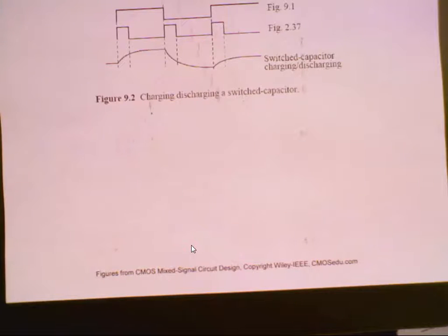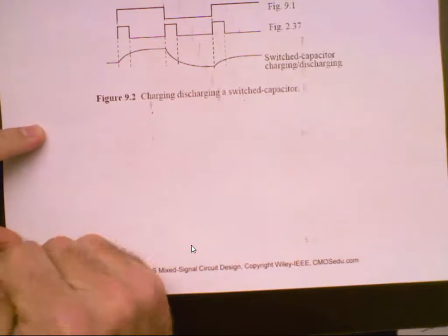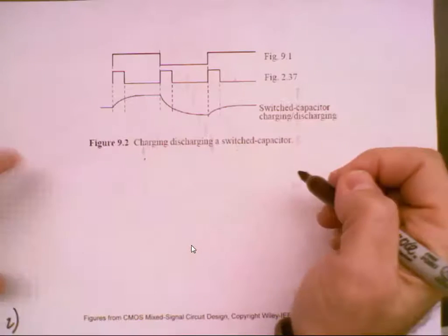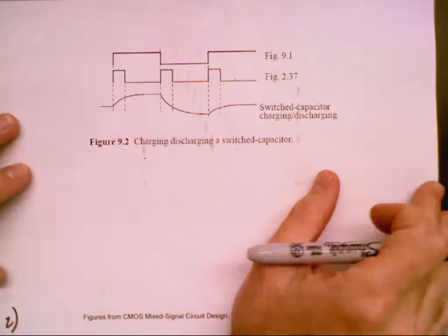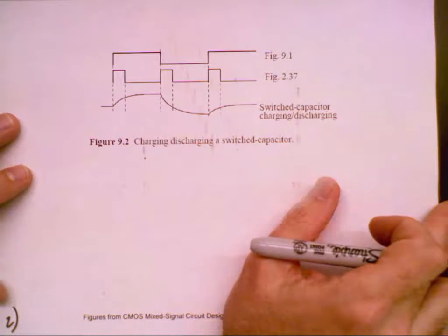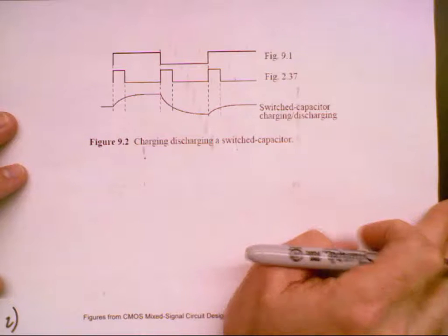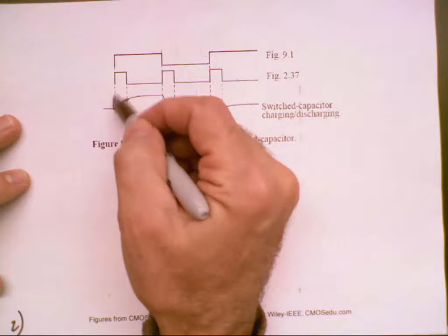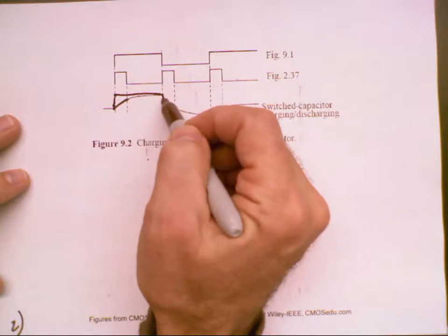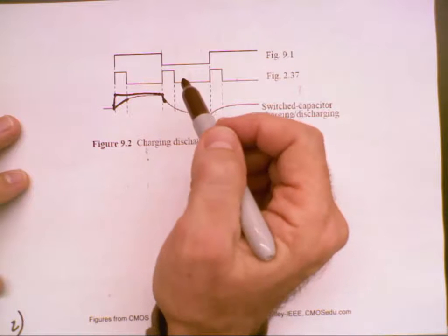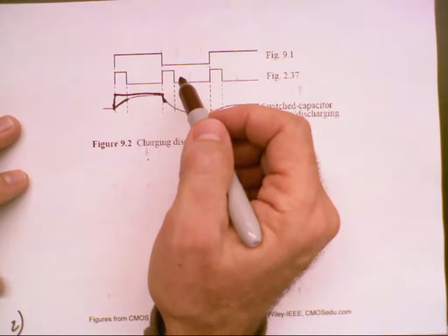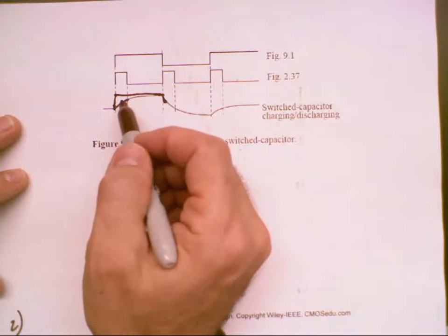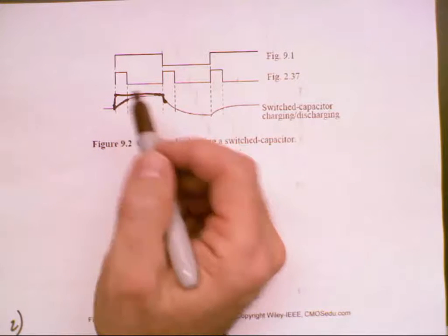One of the things that we have to worry about is the settling time of the op amp and the feedback signal. What I'd like you to be able to qualitatively describe is that you have this RC time here that's not ideal. It's not putting out a clean chunk of pulse that goes like this. Why or why isn't that an issue? Give me a qualitative explanation. First off, let me ask a simpler question.